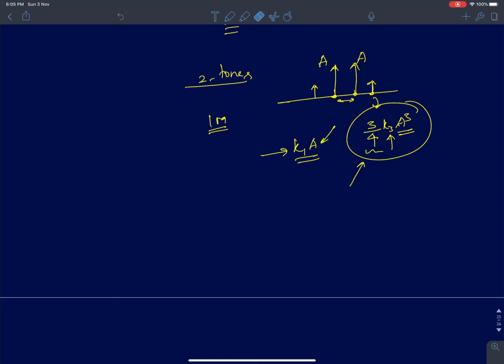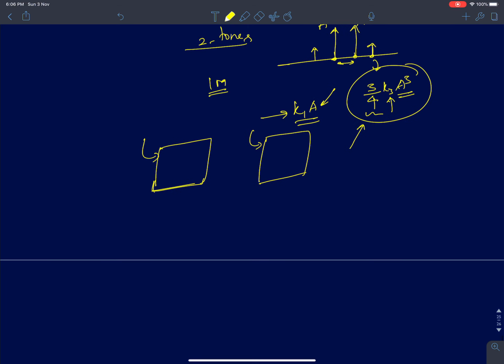Why do we characterize parameters? Because usually it's easier to spec a system, or when I have two receivers, a parameter lets me compare how good each receiver is compared to the other. In the last class we discussed the 1 dB compression point, which was one metric, useful especially for characterizing harmonic distortion.